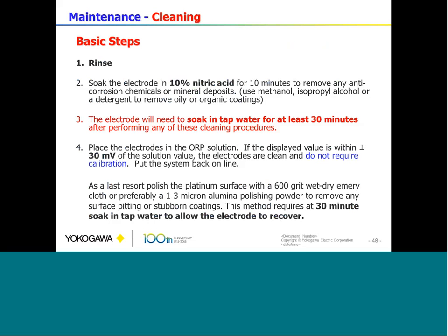There is a difference, though. Once you've done that, the ORP kind of is like a conductivity probe. It becomes, if you want to relate it that way, polarized. So it needs to be set in and allowed to soak in tap water for about half an hour or so to get that out of the way, and so it can be used effectively again.